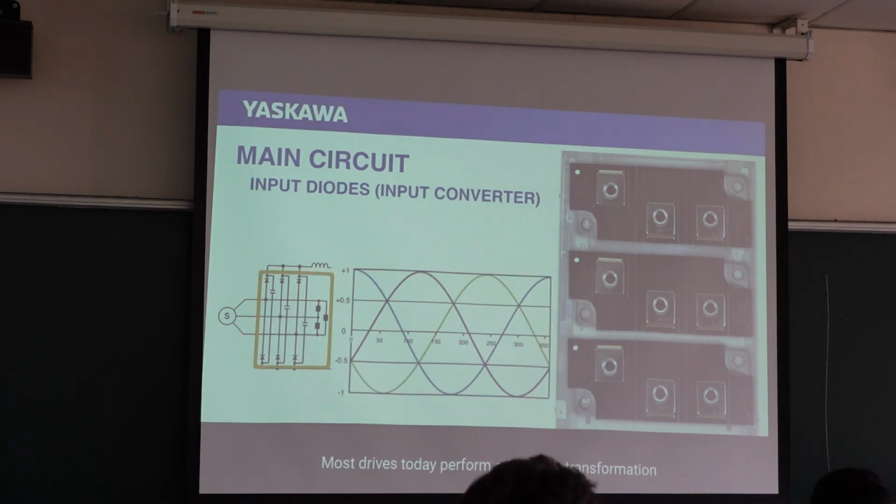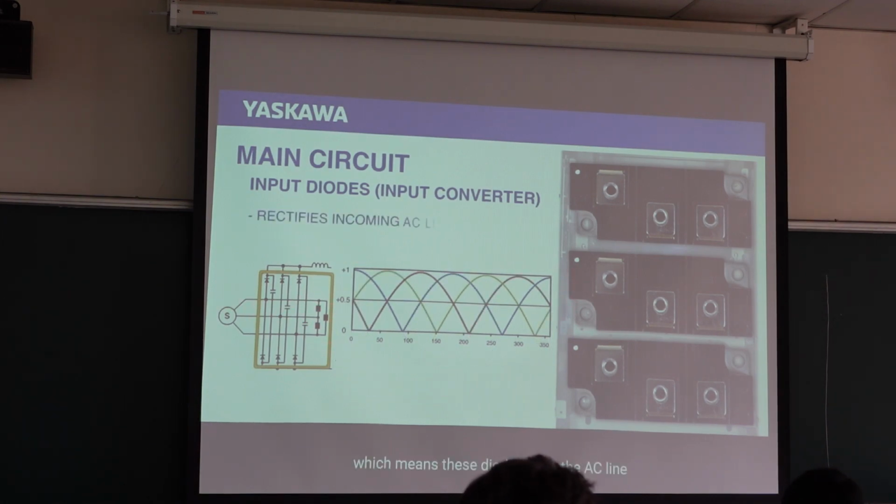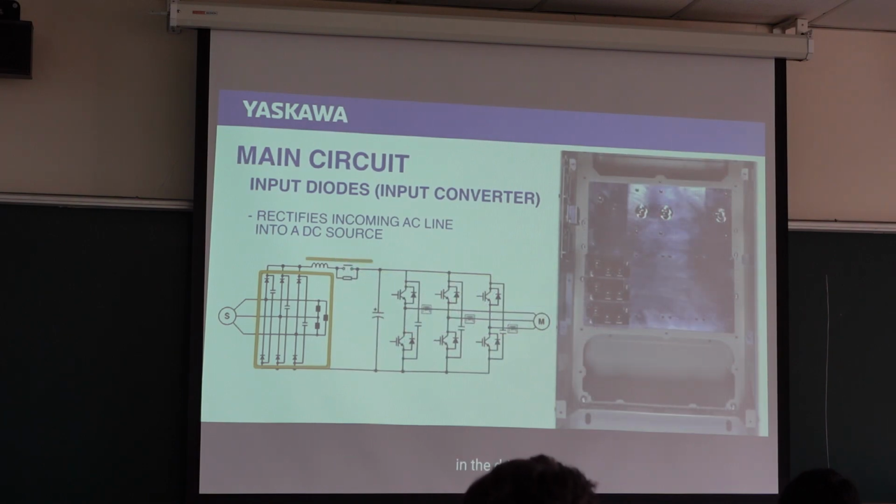AC to DC. Most drives today input AC in the form of full wave. Then we convert it into DC, which means these diodes convert the AC line to DC and create a DC supply. That is the first of the three major components in the drive.